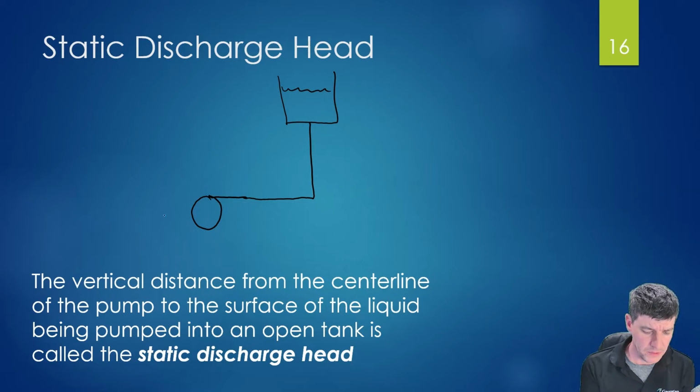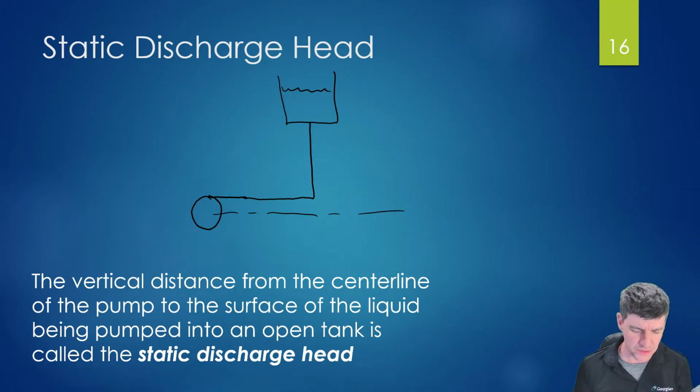So we have our pump, and we've got some center line from the pump, height-wise, so wherever the center of that pump is, compared to the height of the fluid, and the vertical distance here we would consider to be our static discharge head.